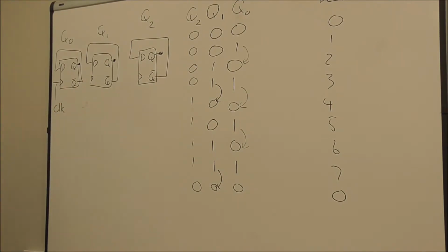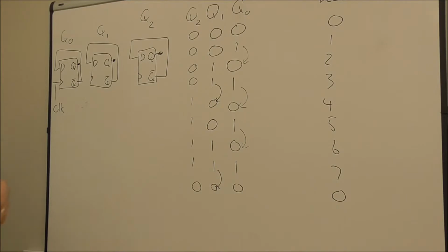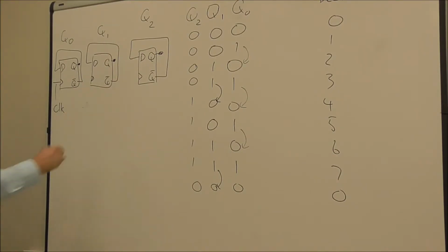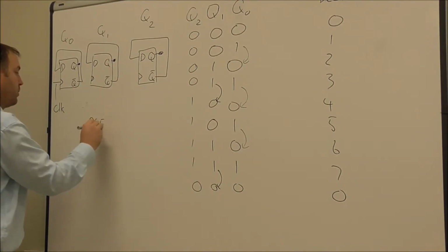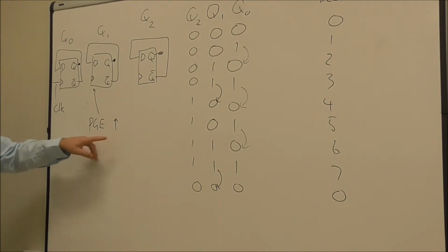Right, so that might just be a 1 second pulse. So 1 hertz pulse or something like that, which would make this one toggle every second. It would see a rising edge every second. And then what we want for the second one is that it changes. So this here needs to see a rising edge, because this is what we call a positive going edge clock pin there, so it needs to see a rising edge.